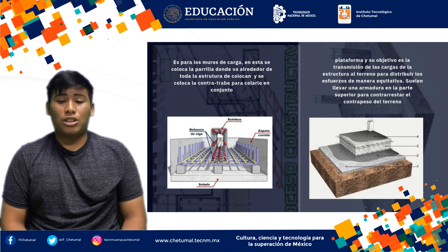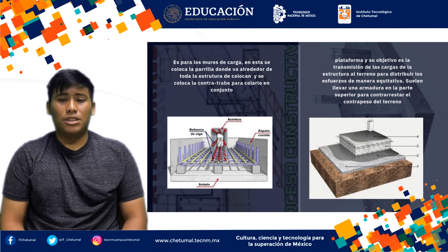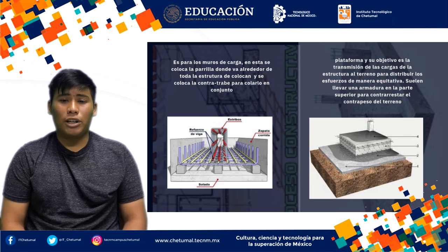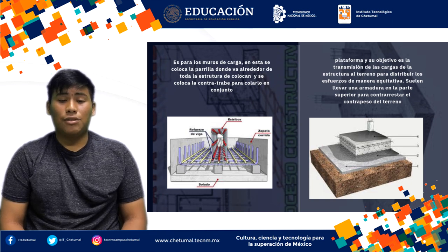We begin with reinforced columns, which are a key vertical building element for the structural stability of any building. 1. Reinforced columns. These are vertical reinforcements placed in the corners of load-bearing walls or between long spans of wall. Their main function is to resist lateral forces such as those caused by wind or earthquakes, and to prevent the walls from collapsing.